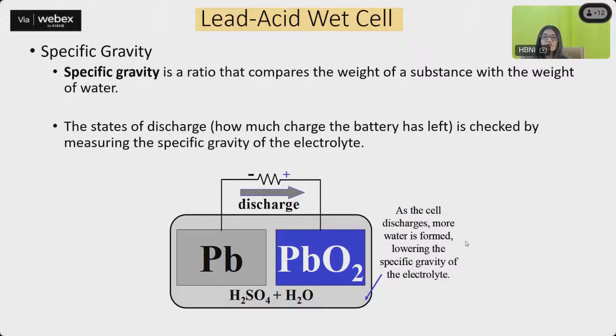And so you get to know whether this battery is charged or discharged, and how much of it is discharged. Now there is one more point you have to understand: in all this lead acid battery, how long can you leave the lead sulfate that is formed just like that? If you totally discharge that battery and then leave it for a very long time without charging it once again, it is very difficult to recharge that battery.